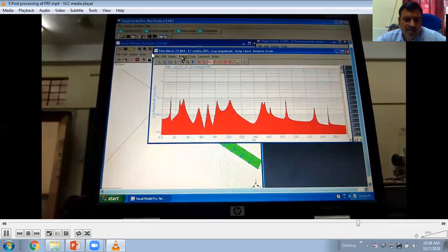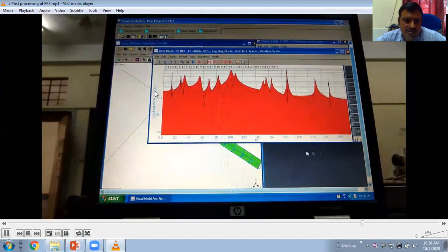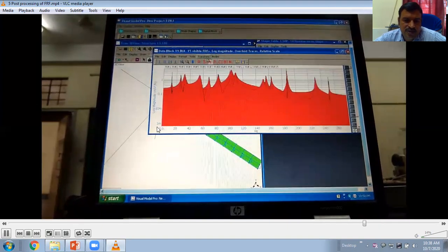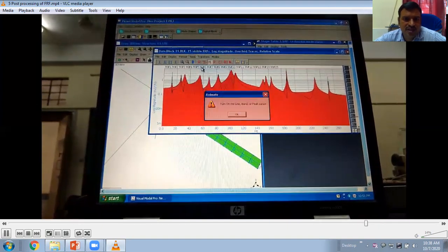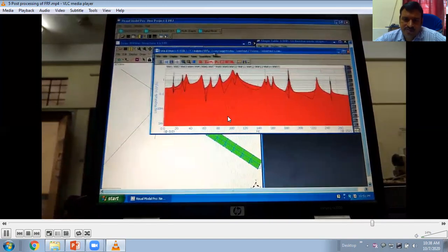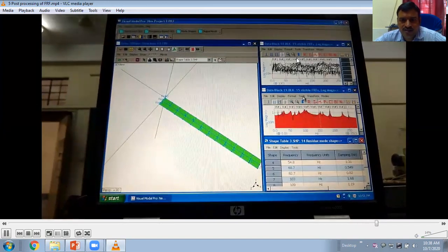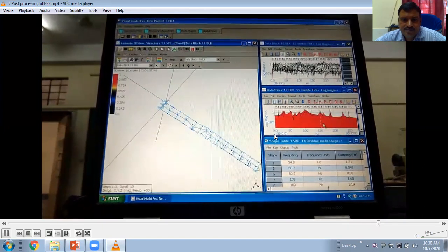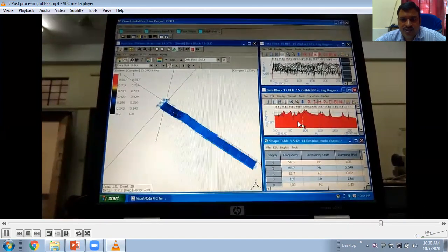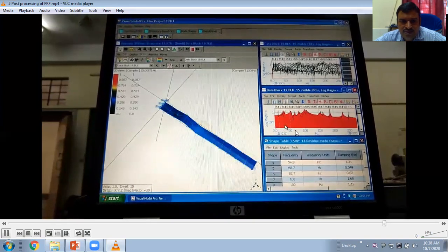Now this is another diagram, here you can see displacement versus frequency. As I told, there are two graphs in FRF, amplitude versus frequency and phase versus frequency. So this is my amplitude versus frequency, and all these things you can see here. Again, using this, when you change the cursor, the vibration characteristic of the beam will also change.